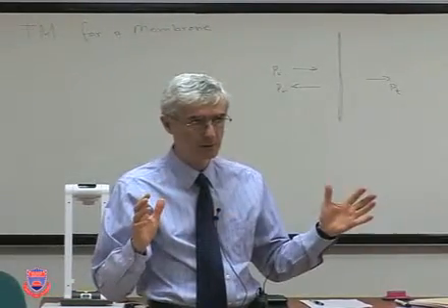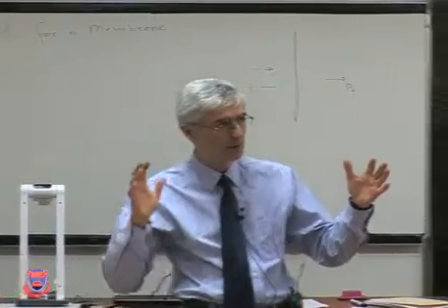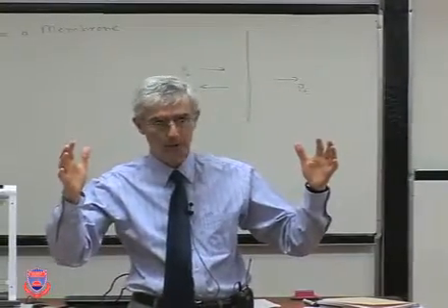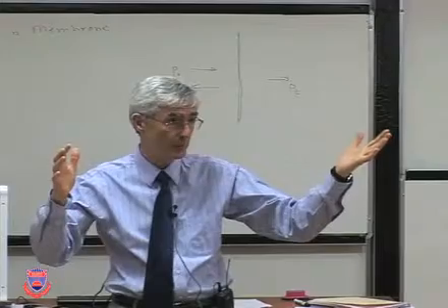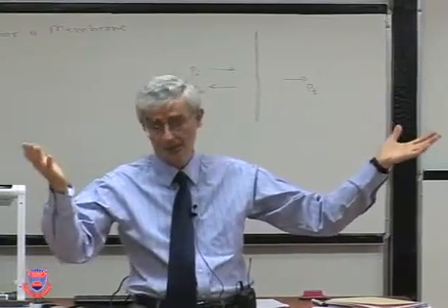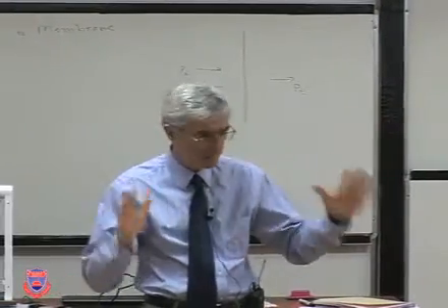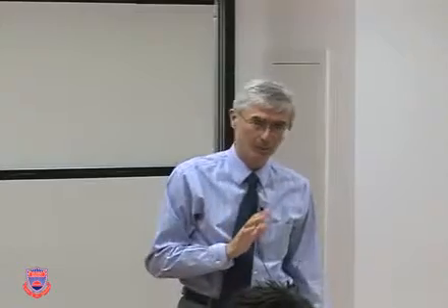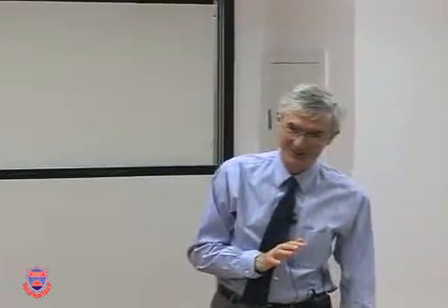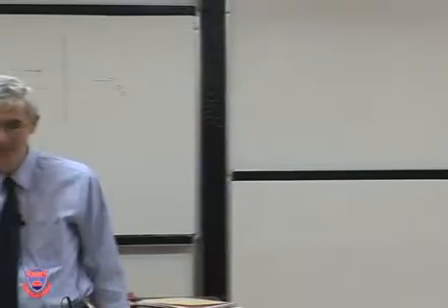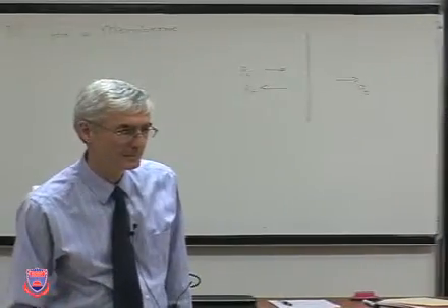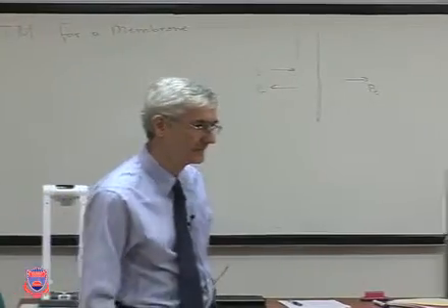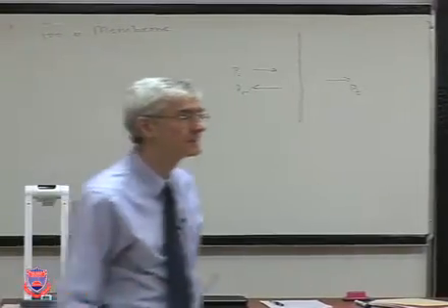So this is a transmission matrix. What are you trying to do? You're trying to relate pressure and particle velocity on one side to pressure and particle velocity on the other side. As simple as that. Okay? Think about it and see what you can do. Write down the usual. Okay? This is the only way you're going to learn these things. Okay? Try. Same properties on both sides.